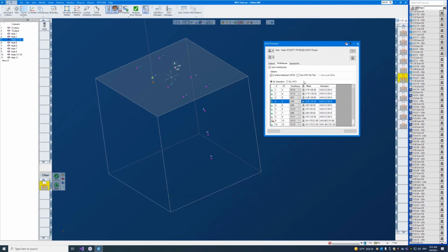They're already in use. And so we'll probably add a feature to do that explicitly, where you could say, for instance, start at G110 for this part. Don't use G54 through G59 because those are already in use.